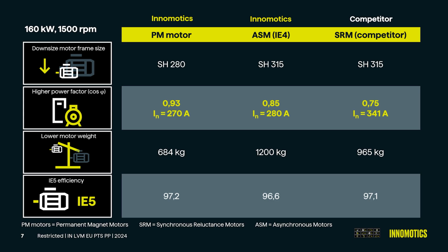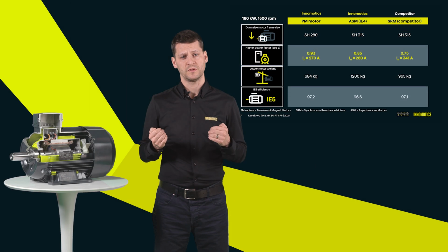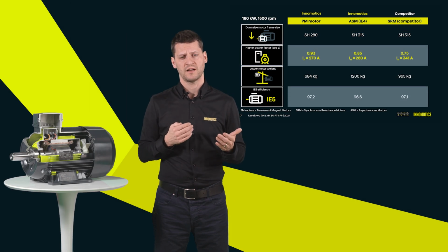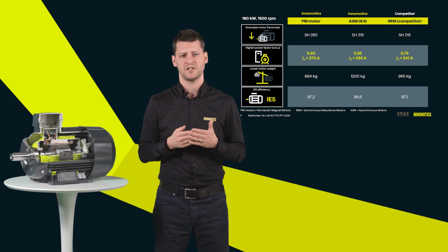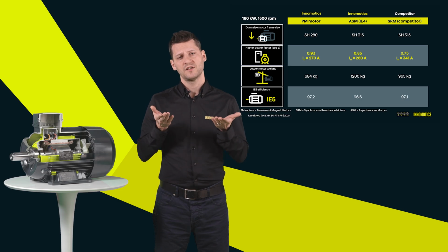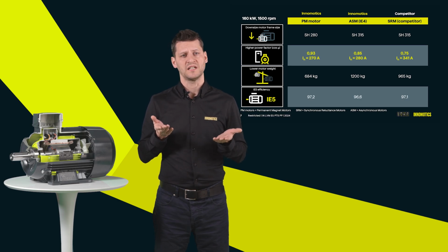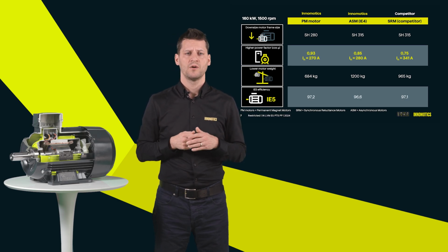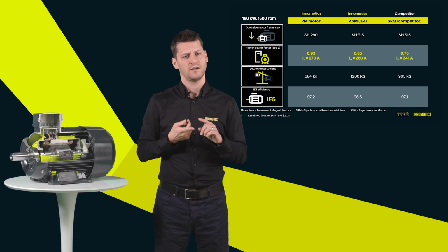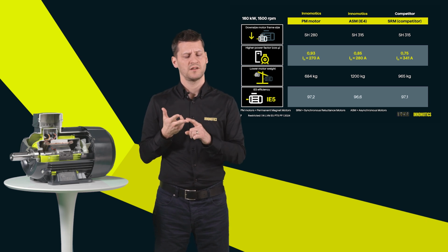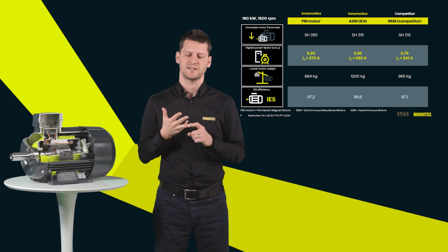along the drivetrain. But if you choose the synchronous reluctance technology, the poor power factor, which we mentioned as a clear disadvantage of this technology, raises the nominal current, and that means you have to change all the electrical devices which are current related. Drive, cables, and also the protective devices.